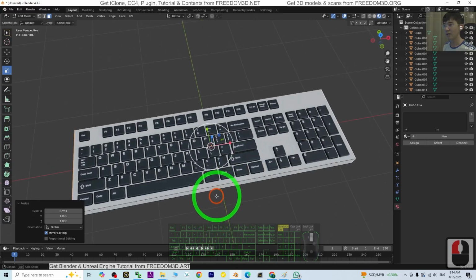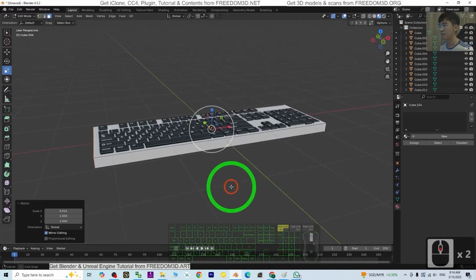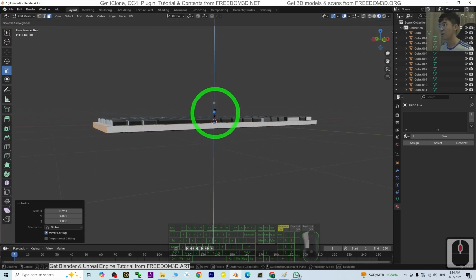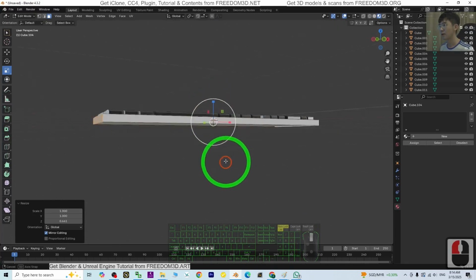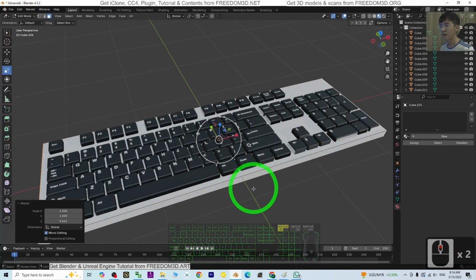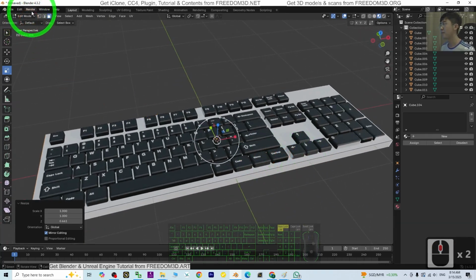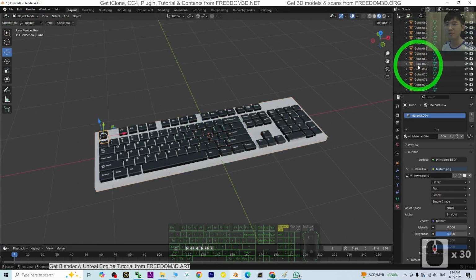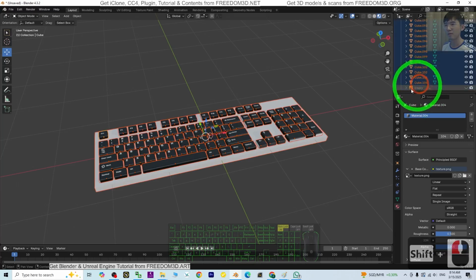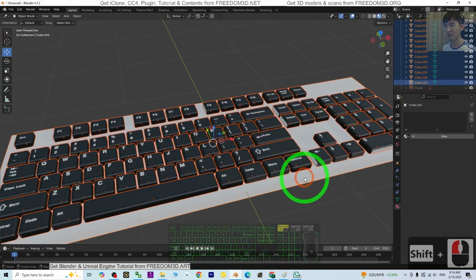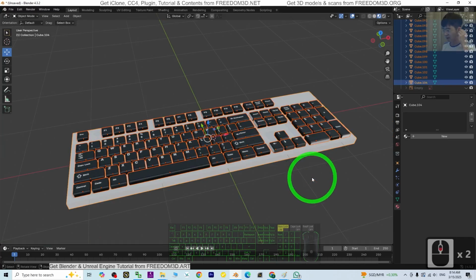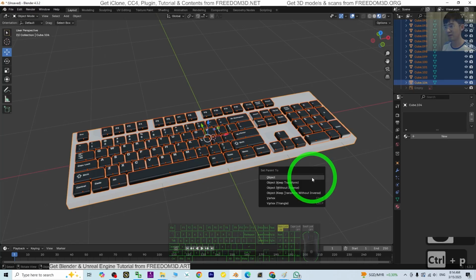Okay, so next, make it higher. Alright, once you've already done this step, back to the object mode. For all of this, we are going to just make sure it attaches to this plane. I press Shift D to click the bottom part. Then Control P, the object.